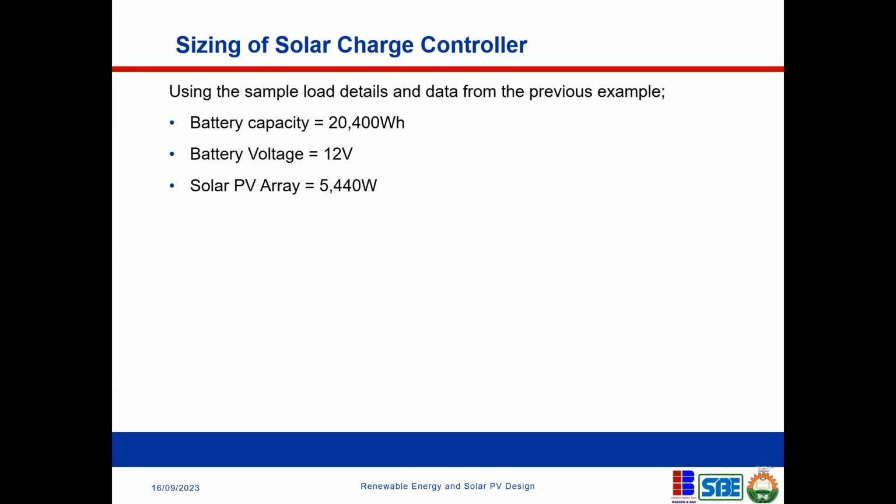You need to know the capacity of the charge controller and be sure that the solar panel that you're loading to that inverter is not oversizing, I mean, not higher than the capacity of the charge controller. Of course, they will state it. For hybrid inverters, it will be stated the amount of solar panel you can load to that charge controller.